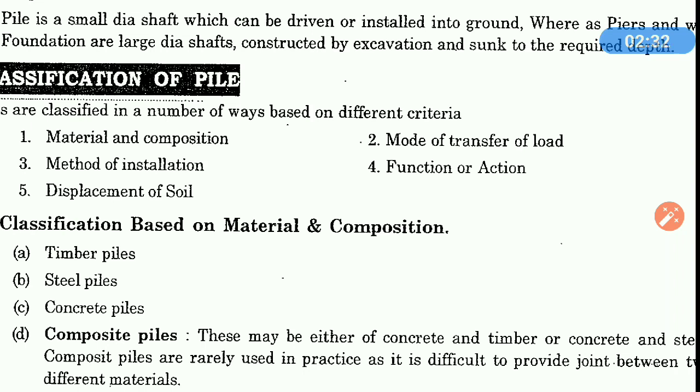In this we classify the piles based on the method of installation, like in situ piles, cast in situ, or bored. When bored, we can bore piles in two ways, like screwing or by providing impact through a hammer. And then functions or actions.